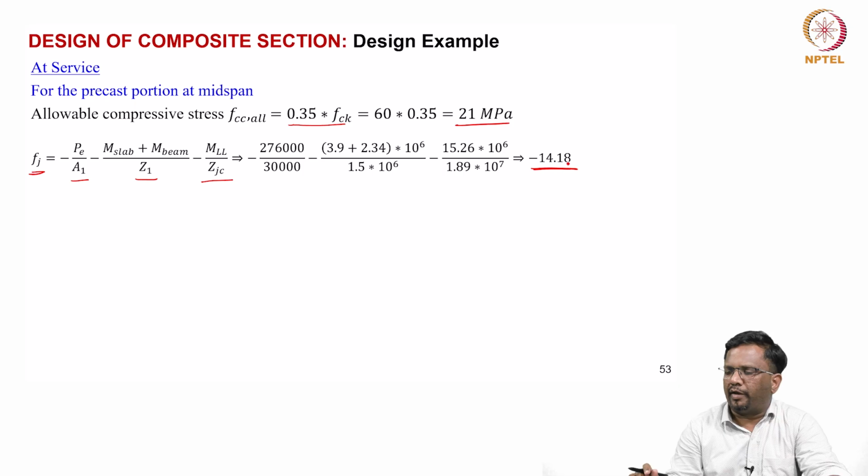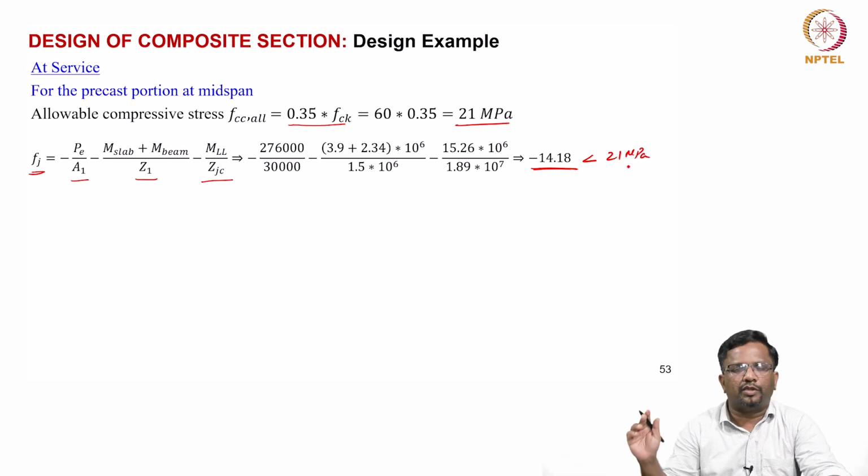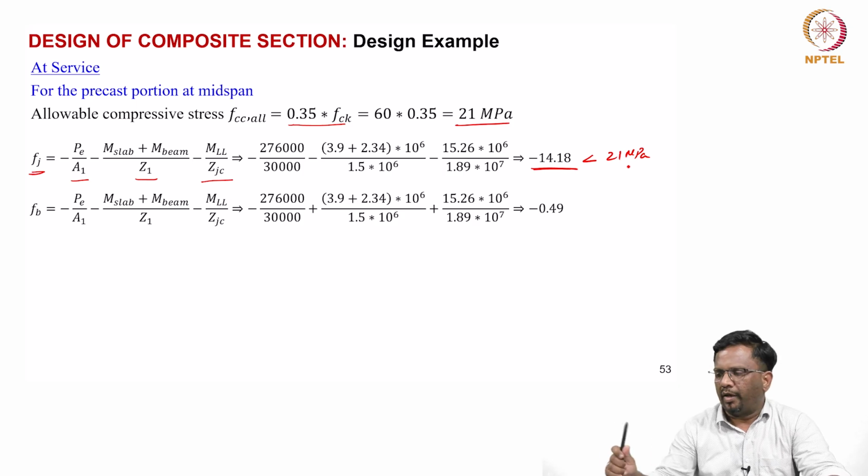Now, I am getting a stress of 14.18 megapascal. Again, this is less than 21 megapascal in compression. Okay, 14 is less than 21. So, it is okay, right.